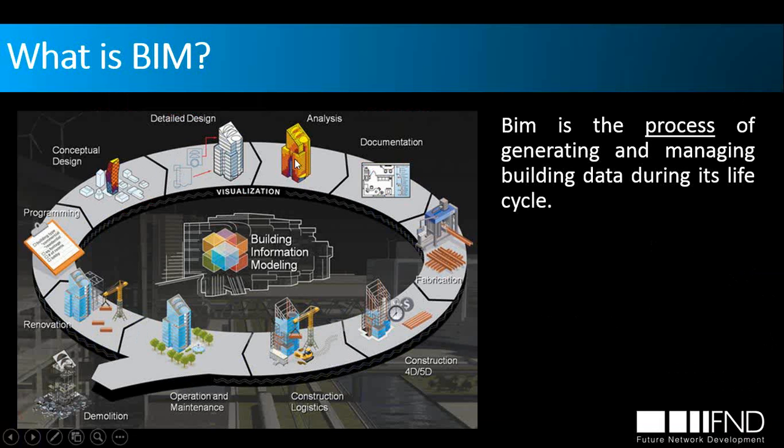We can also have analysis, such as light analysis and energy analysis over the model, testing what the best solution is. And during the documentation, when we know more about the details, we can also enter into the model all necessary information, attaching it to the objects used in the model. We can also use the BIM model during the fabrication. We can get all the necessary dimensions, for example, or the finishing details, how it should be produced to use in the construction phase.